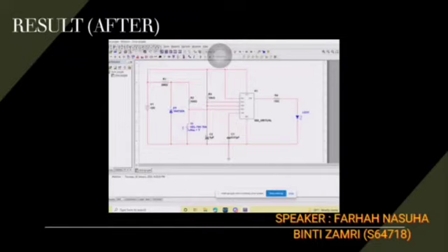The resistors use different values such as R1 equals 390 ohm, R2 100 ohm, R3 10k ohm, and R4 10 ohm. The RTD selected here is HEL 700 TOA with a maximum operating current of 2 mA.